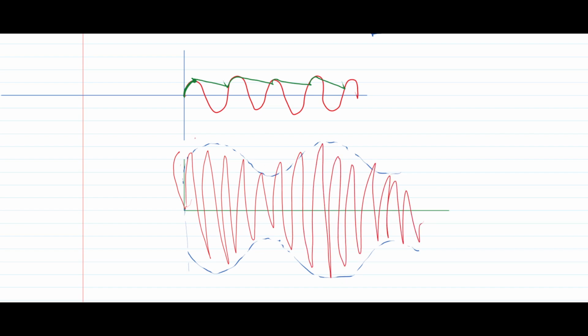So the amplitude of the carrier signal is being modulated, and you need to obtain the output. What will happen? The capacitor will charge, discharge, charge, discharge. It will charge very quickly but discharge slowly. Charge quickly, discharge slowly. Similarly, this will happen throughout.